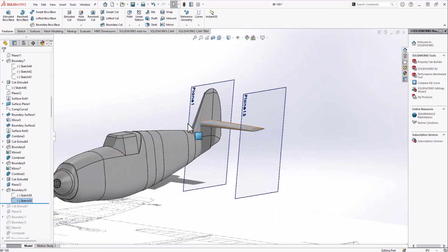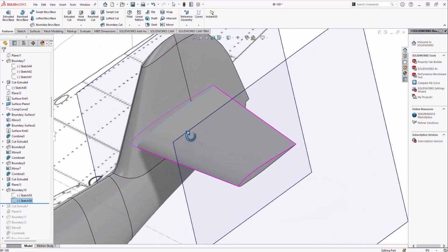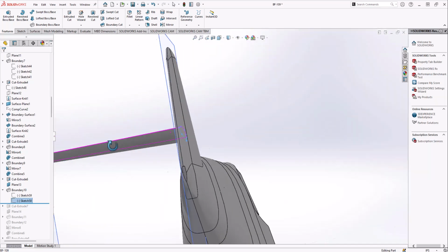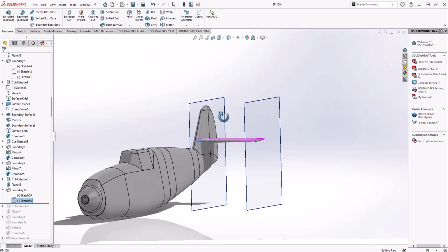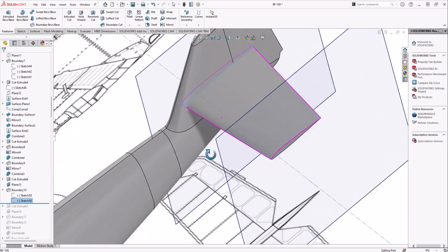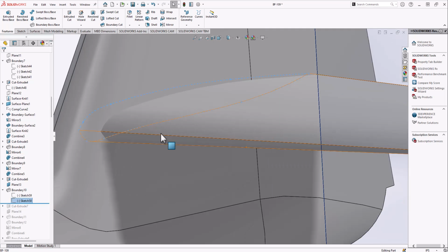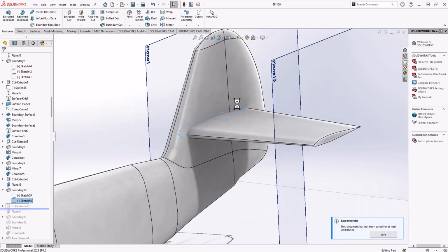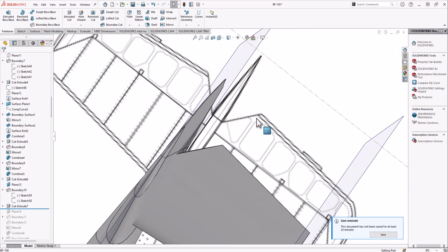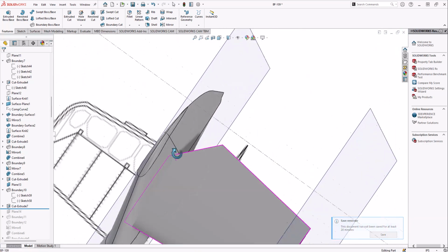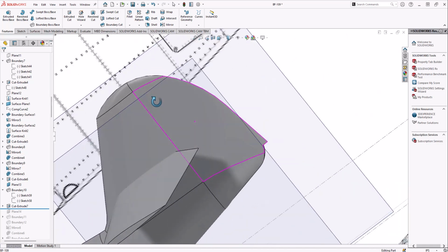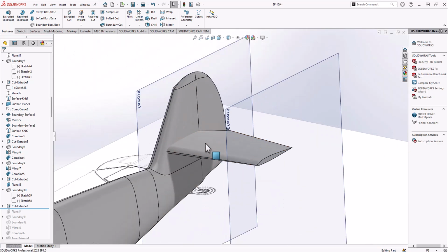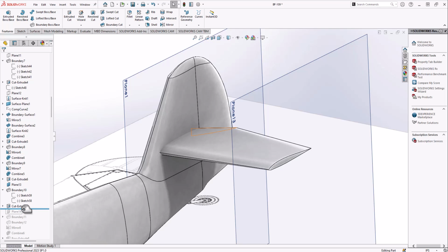That way I can do the boundary between the two. Here it's basically a loft at this point because I'm not using any of the normal features, but it sets up that kind of shape while preserving the airfoil design. And then I subtract because there are some details, like here where it comes together and closes off, that way the yaw control actually has yaw control and doesn't interfere with the pitch control.